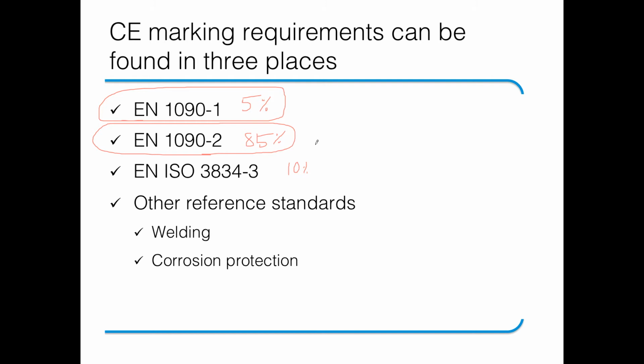You must have a responsible welding coordinator. You must perform welding according to the WPSs or welding procedure specifications. And all of those are going to take time. Not just your time, but in most cases you must involve a third party in the process, and then coordinating everything and getting the third party involved is going to take a lot of time. But still, if you know what you're doing, it can be done quite fast.